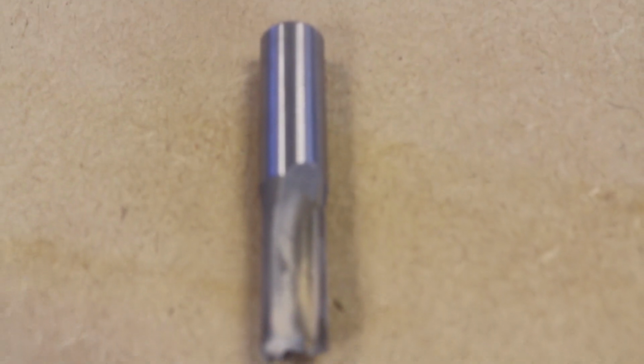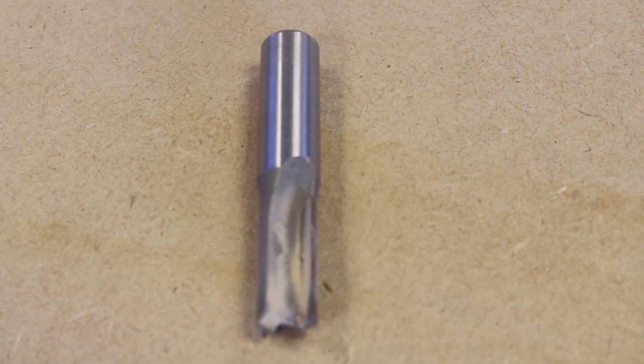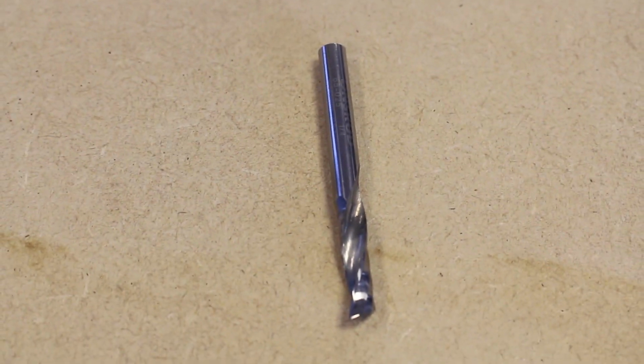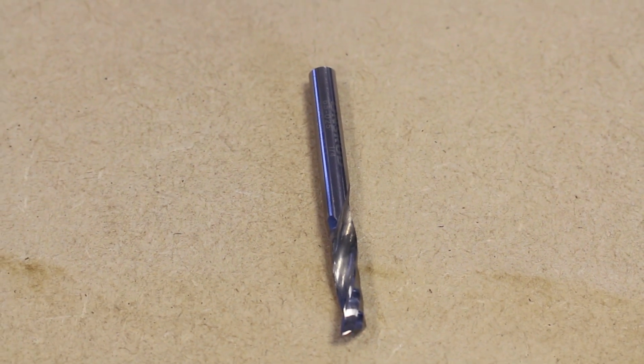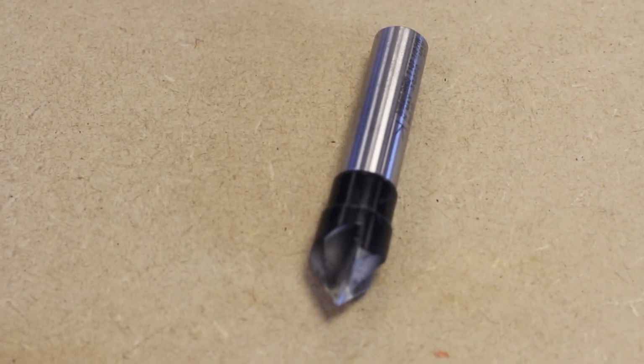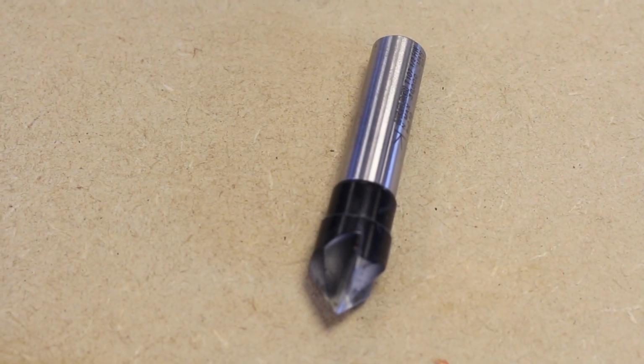Okay, so we're using MDF, and the tools we're going to use: a 1/2 inch end mill, to basically hog out the border. Then we're going to use a 1/4 inch end mill as part of our VCarve toolpath, to clear all of the flat areas that we can. And then we're going to go in afterwards with a 90-degree 1/2 inch V bit to create the actual VCarve part. And then to finish, we're going to look at using a bull nose tool to create the flutes so that we can easily access our paper within the print block.